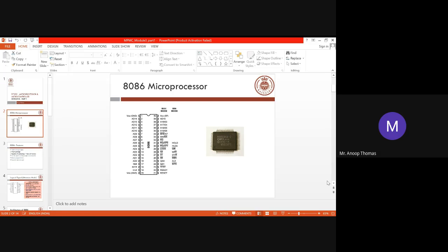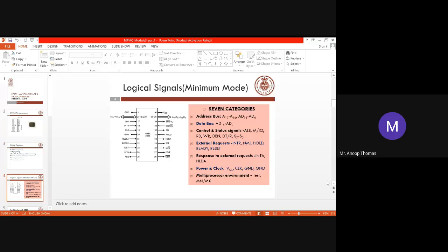Okay, so in today's class, we will mainly be dealing with the architecture of your 8086. So these were the things which were discussed. We also had status signals. We had around 7 status signals, of which the first 3, S2, S1, S0, were similar to the S1, S0 seen in your 8085. They tell whether you have a read operation, write operation, memory operation, an IO access operation, an interrupt acknowledge operation, or something related to halt. So it gives you the idea about the state in which your microprocessor is. That was S0 to S2.